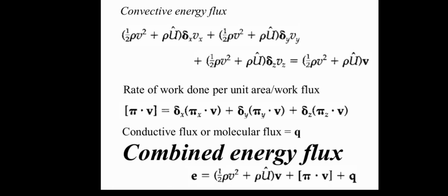It is also mentioned that the rate at which work is done is the force acting on a moving plate times its velocity. When considering the fluid between moving surfaces, the viscous dissipation becomes significant and is represented by a volume heat source term SV, which appears naturally in the energy balance when using the combined energy flux vector.